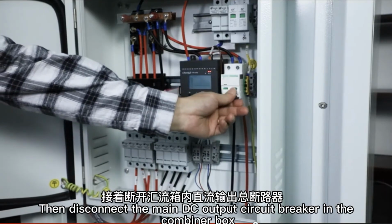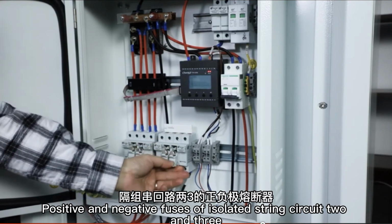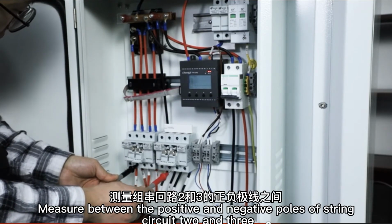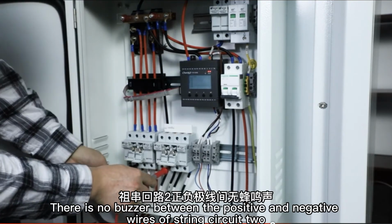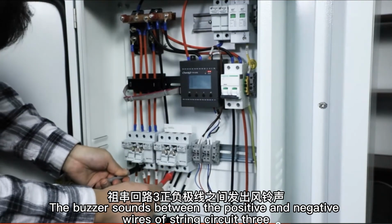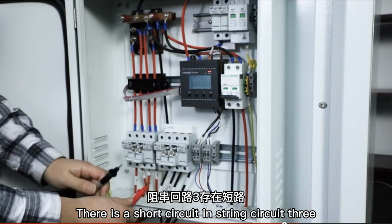Then disconnect the main DC output circuit breaker in the combiner box. Remove the positive and negative fuses of string circuit 2 and 3. Use the buzzer gear of the clamp meter. Measure between the positive and negative poles of string circuit 2 and 3 to see whether it is connected. There is no buzzer between the positive and negative wires of string circuit 2. The buzzer sounds between the positive and negative wires of string circuit 3. Description: there is no short circuit in string circuit 2. There is a short circuit in string circuit 3.